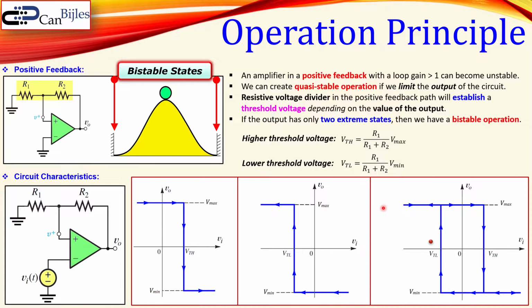This is also called, here, two nodes. We will call this the hysteresis. So we have a safety region, which is very important in order to not have multiple triggering by some noise or interference. Let's see about this hysteresis in more detail in this next discussion.